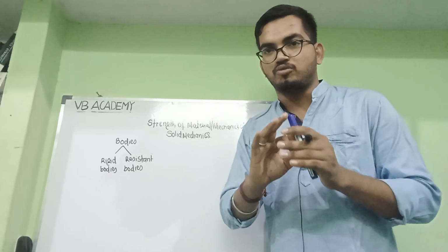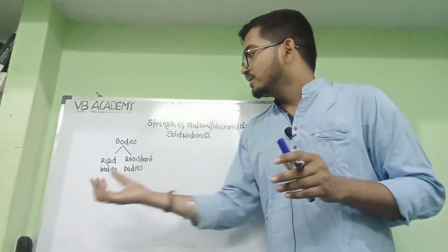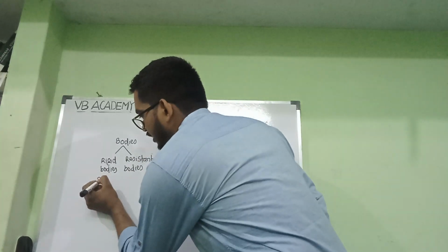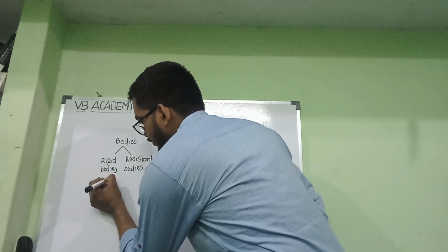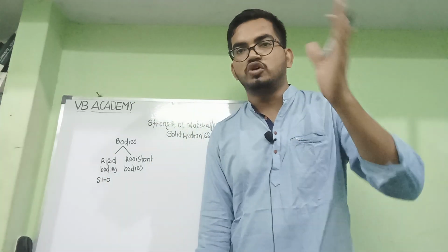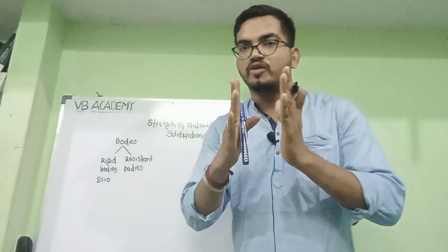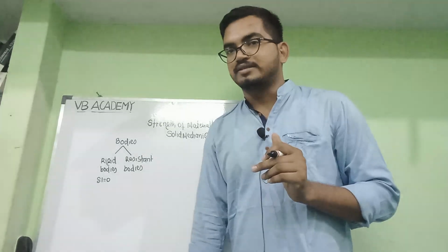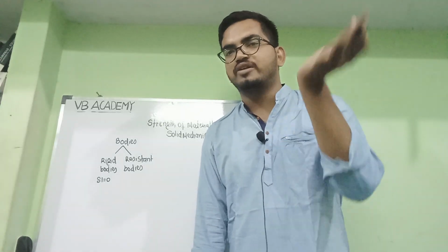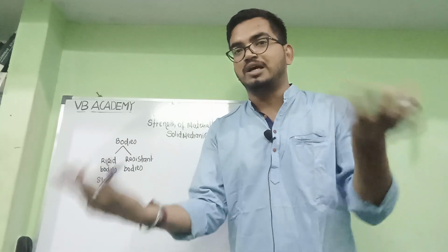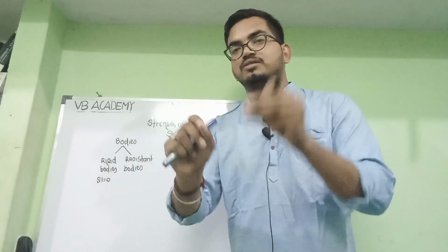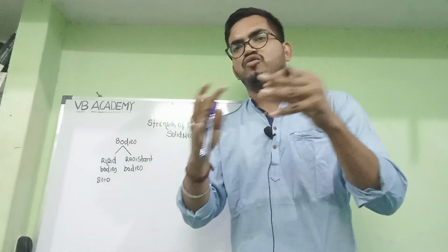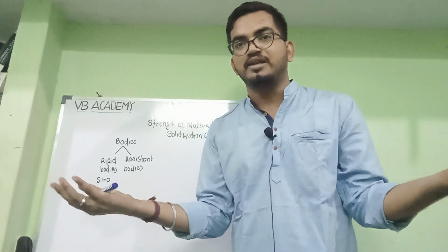No such body called a rigid body exists, but for our assumption we will assume that this is a rigid body, where delta L, the change in length, will be 0 whenever the load is applied on the body. Clear? You are getting the point, right? So basically these rigid bodies we will deal with in engineering mechanics. We won't consider the deformation, where the load is acting on the body, what the deformation is and all those things. We will simply act the load on it and find the resultant. Clear? With a system of forces acting on the body, we will find the resultant, in engineering mechanics.